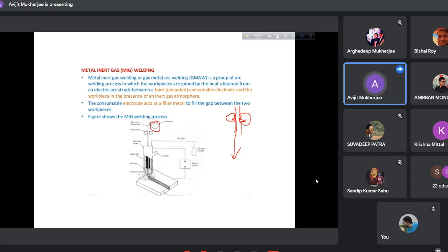And in the workshop, if you observe this gas MIG, the spatters will come out. Yeah, sound will be there. You can also observe what is going on inside, because there is a clear gas shield, gaseous envelope. From this envelope, atmospheric contamination is prohibited, but you can observe what is happening inside.